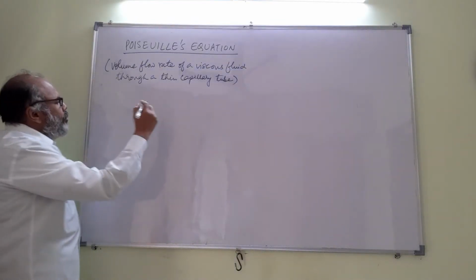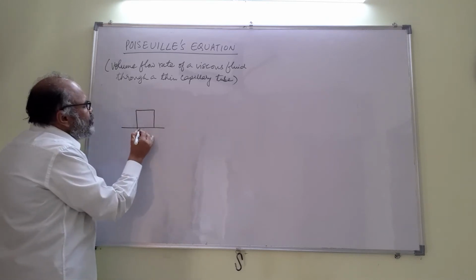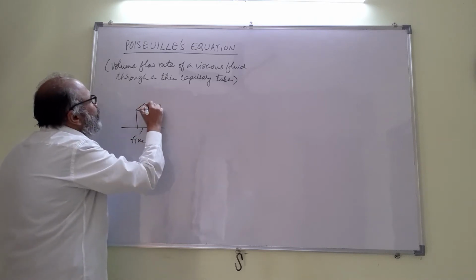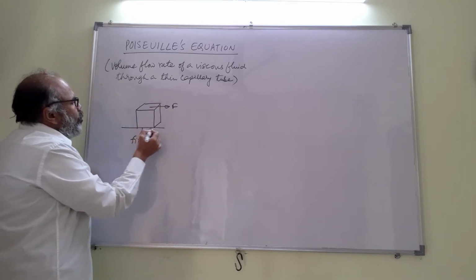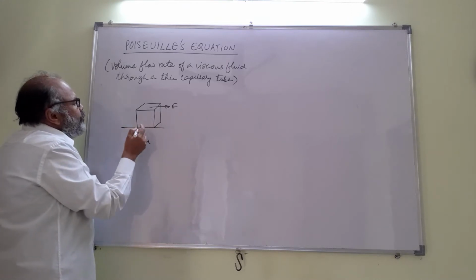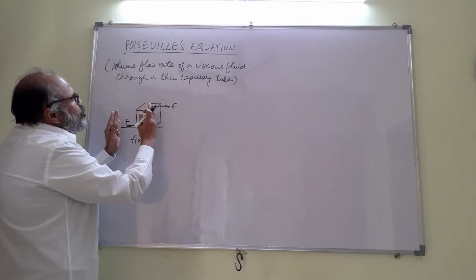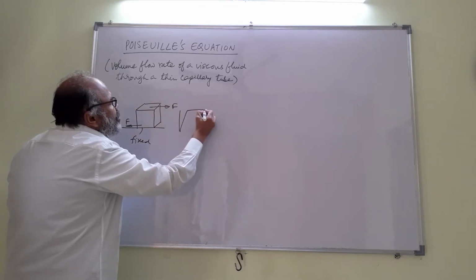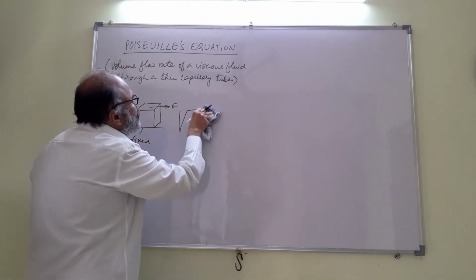Before we go to viscosity, supposing we had a cube which is fixed here, and we apply a force F like that on it. Obviously, the surface on which the cube is fixed will exert a force like this. There will be a couple like this, and this cube will get sheared. The square becomes a rhombus.